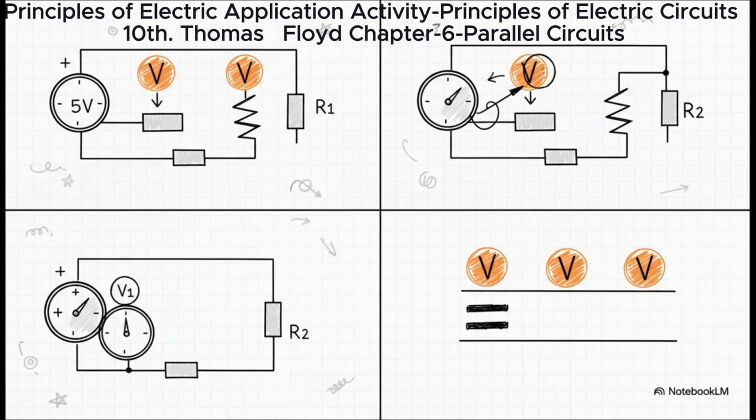Next, number 2. A voltmeter across R1 reads 118 volts. What's it going to read on R2? Well, since they're in parallel, it's got to be 118 volts, which also tells us the source voltage is 118 volts. Good.